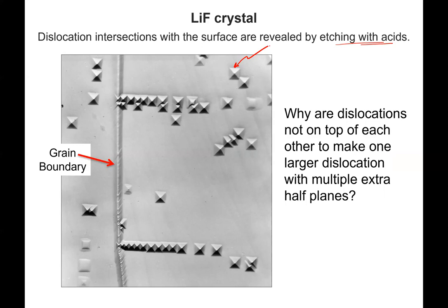So we have here the lithium fluoride crystal, which is face-centered cubic, and we are putting an etchant on the surface so that optically we can see features. So the first thing that we see are these pits, okay? And these are four-sided pyramidal pits, right? You can see that. And each of these surfaces that you're seeing here are a 1-1-1 type of surface, right? Remember, these are low energy surfaces.